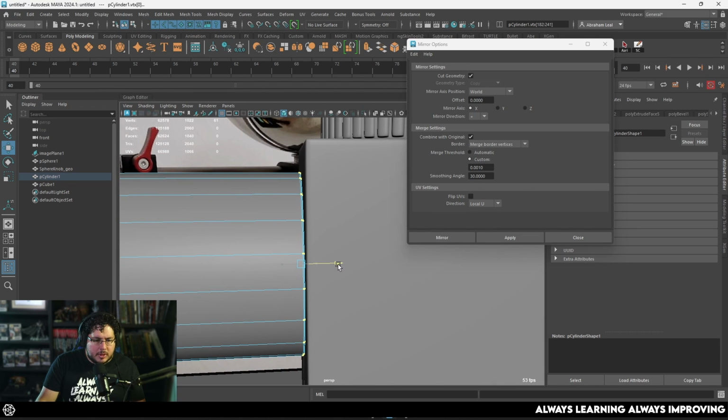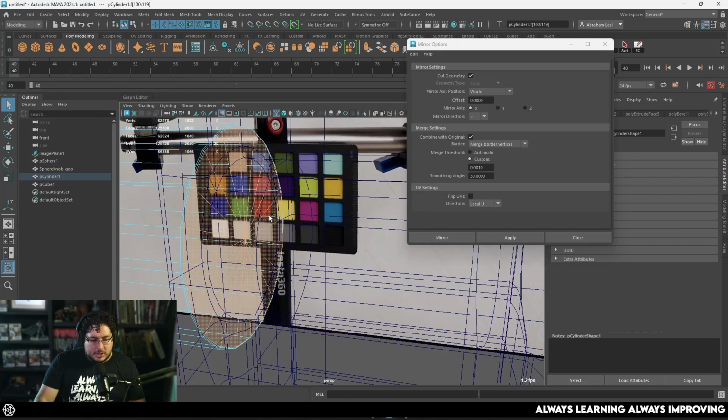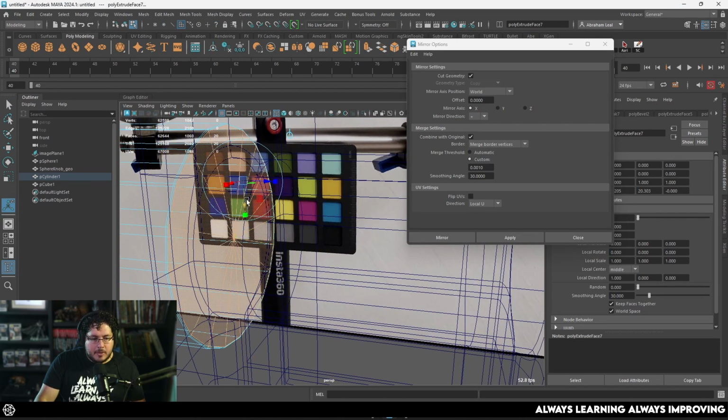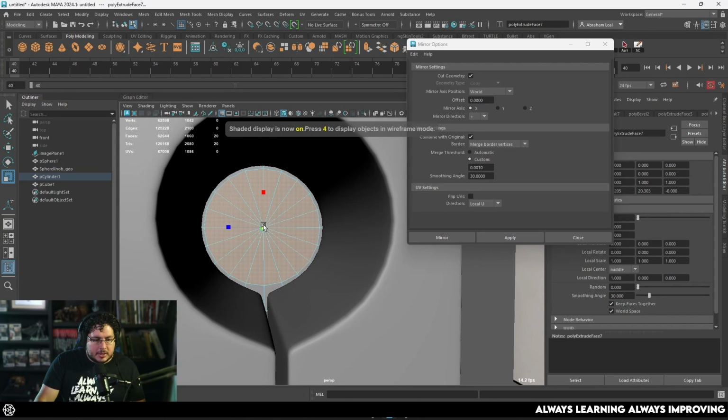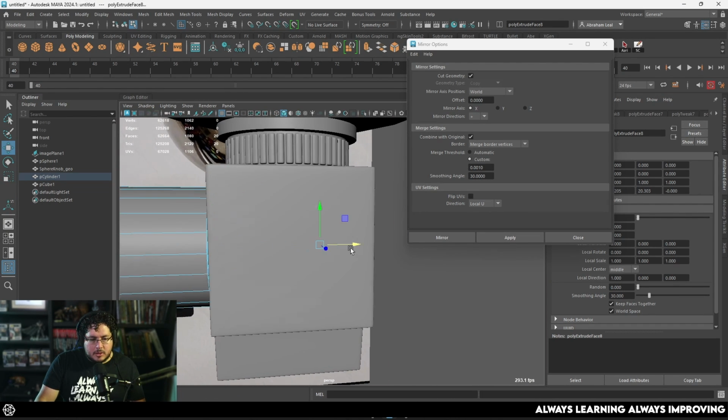Keep it right around there, similar to the other one. Grab that vertex right there. Control F11 to select all of the vertices. Control E, R, we scale down until we get the size of the hole right there. Control E, and we push out.